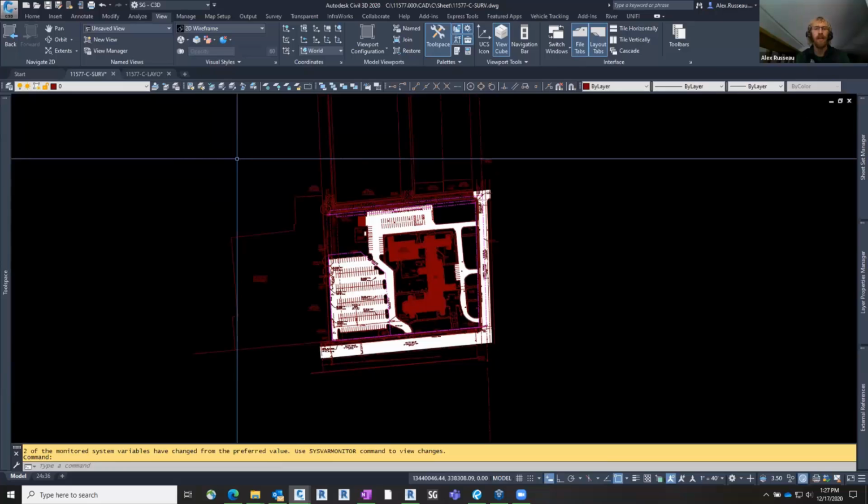The problem that usually happens between Revit and Civil 3D is that Civil 3D has its own content that is native to it, and Revit doesn't quite understand it. I'm talking about points and surfaces and then pipe networks. Those are three things that are Civil 3D specific that Revit tends to struggle with. So if you were to purely link a Civil 3D file from the civil engineer directly into Revit, you're going to get all sorts of warnings. There's going to be a lot of issues with those files. Another thing that isn't great with Revit is the 20-mile radius.